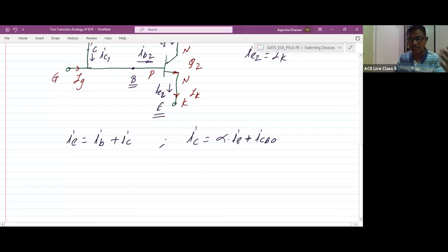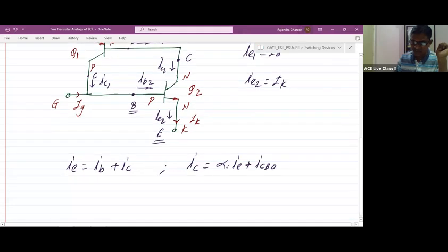In the transistor we have the alpha and beta terms. And ICBO is nothing but the collector to base leakage current when the base terminal is open. Generally in transistor operation we neglect this term, because it is a leakage current only, a very small value. So these two expressions we are going to use from the basics of the transistor. Now, this is the expression for any transistor.